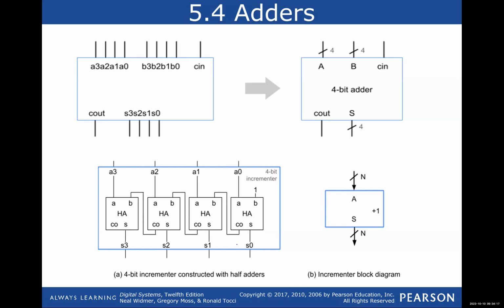That's for the half adder. I have the sum, and I can take the carry over to be my next number in the half adder. So if I want to do just an increment, I can just create it using the half adder. I don't need a full adder because I'm not adding 2 numbers. It's only 1 number plus 1.